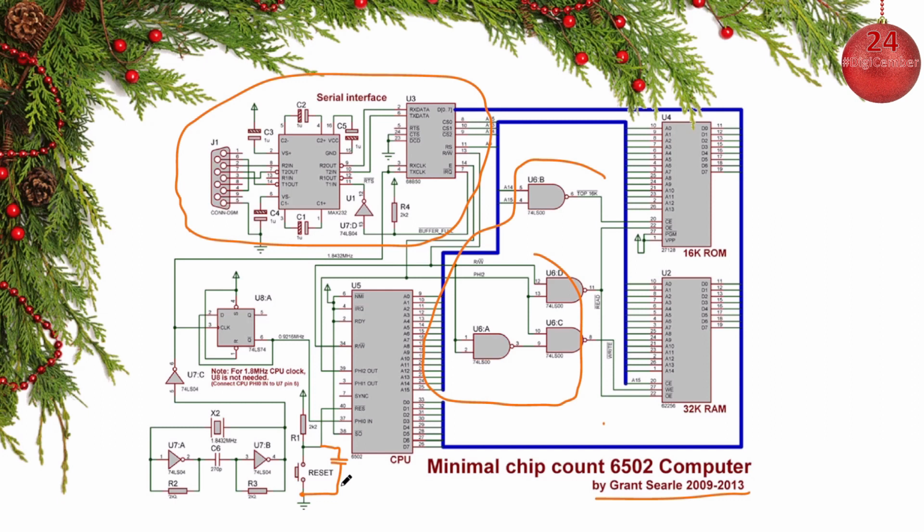In the 6502 design, it is specially mentioned that you should keep this low for 2 to 5 clock cycles to make the CPU be able to fetch the addresses up in the address space and to make everything ready to do that fetching. So all in all, there is rather a lot to it, but I do think that our design will work with some small tweaks.